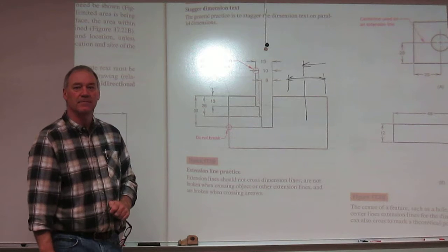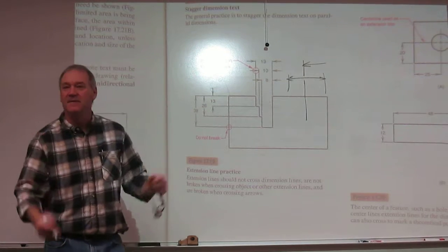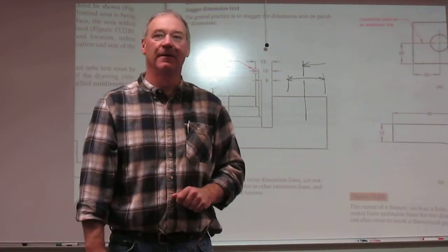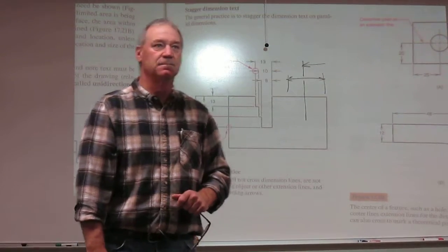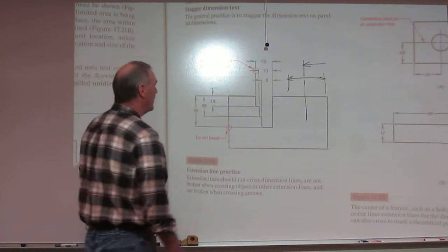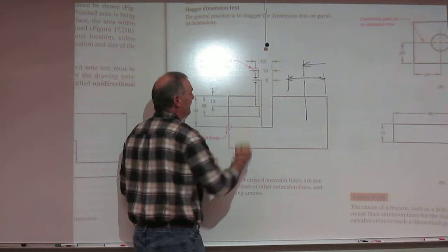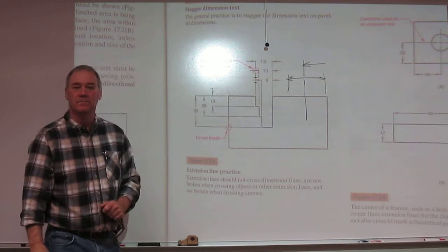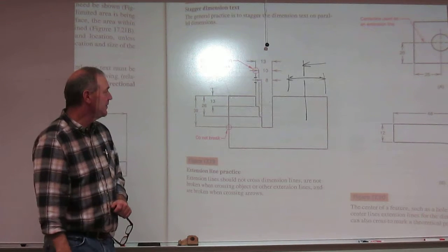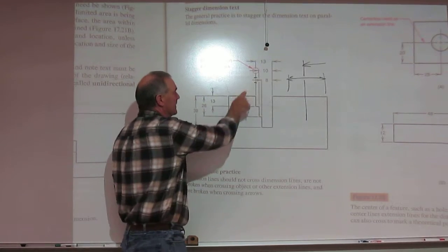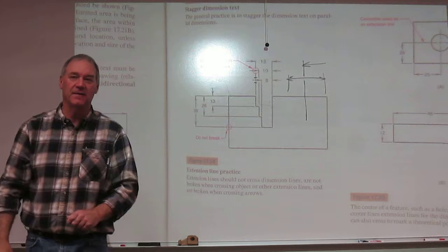How big is a break? Standard 1/8 inch is fine. That would give you a 1/16 on both sides of that line. So make your break 1/8. That's the only time we break it, and it's just so we get good clarity. Like this one, in my mind, that one right there should be broken, where it's hitting that dimension line. See how he doesn't break it here, because he doesn't hit the arrow?